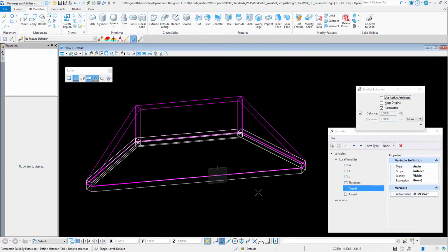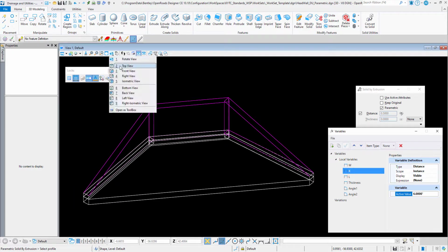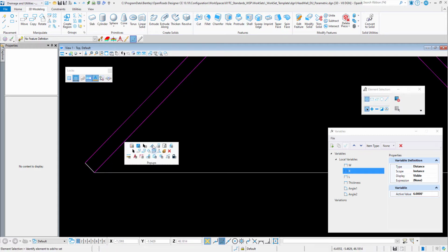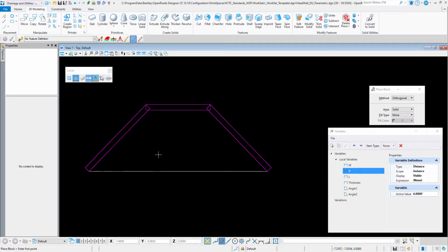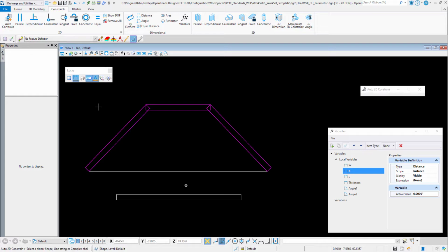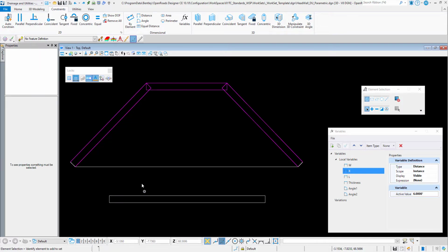Now I'm going to add the thickness of that bottom plate. And then I think the last thing that we're going to want to focus on after we do some testing is a toe footing. And so for this footing, all I'm going to do is just draw that one rectangle shape. Constrain it, the thickness that I want it, auto constrain the edges or the perimeter.